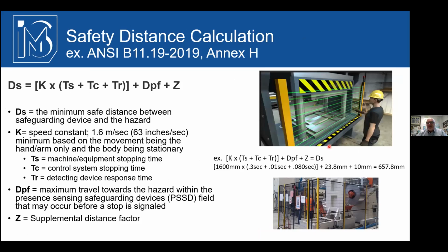from the hazard? In this case, the example would be a detection device. When I breach this light curtain, how fast does this machine have to come to, let's say, a stop? Fully stopped is a safe state. How fast do I need to get to that? This used to be a stop time calculation, but sometimes we're not stopping. You'll see later with a category 2 stop, we may just be slowing down, but basically, how soon do I need to attain safe state?